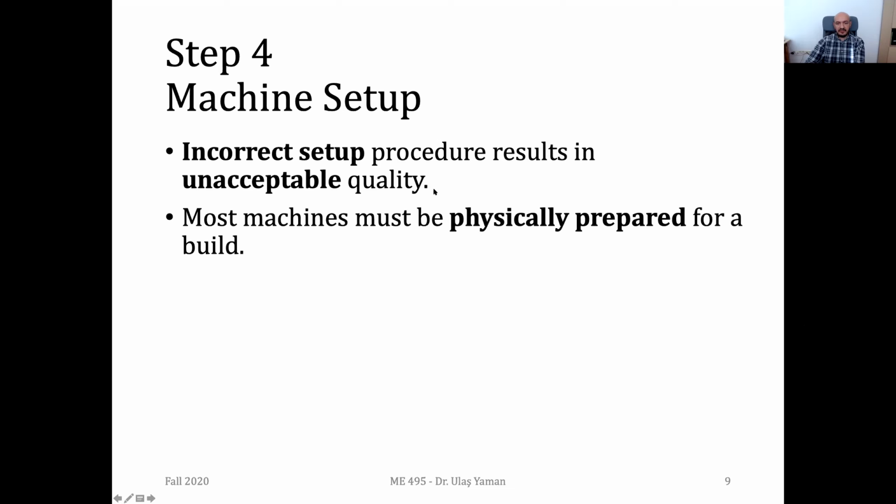And obviously, before starting the manufacturing, you may need to do some physical preparations. You need to adjust the level of your plate. You need to clean the nozzle, maybe clean the table. So these are things you need to do physically before starting the fabrication. Yes, your material may be finished, so you need to have a new bunch of material, new cartridge of material, new tank of material, depending on your fabrication process.